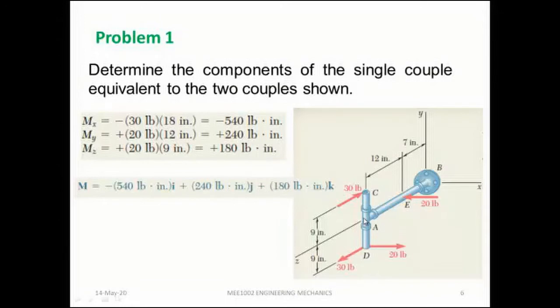And the third one, this force now formed a couple, another force is here. That force and this force will form a couple because these are parallel and opposite to each other. The perpendicular distance is 9 inch, so this will form an anti-clockwise couple.